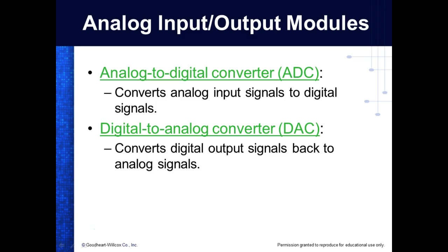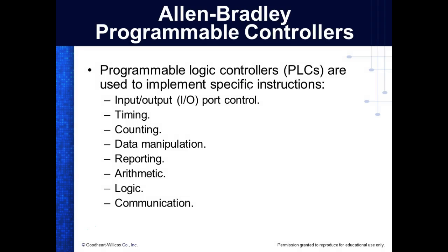This one has 2 analog input ports, but this little module we stuck right there gives us an analog output. So in my program, I would store a binary number into that port, and it would automatically generate a voltage that was equivalent to that binary number.